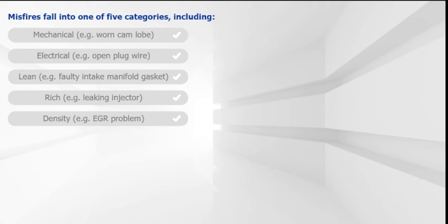Dilution, a condition caused by too much recirculation of exhaust gases into the intake airstream. This condition is typical on vehicles with EGR valves. Hyundai uses CVVT to fulfill OBD EGR requirements. Flooding the intake airstream with recirculated exhaust gases causes the combustion chamber to lose combustion heat, which renders the air-fuel mixture inactive, because the density of the chamber has been lowered to a point where the flame or ignition propagation is not possible.